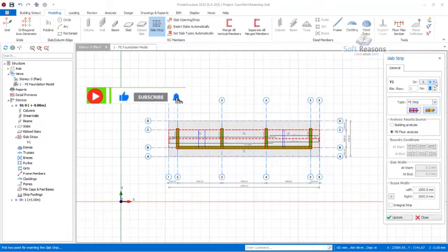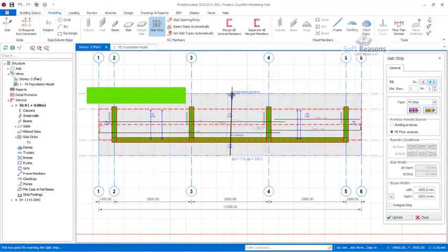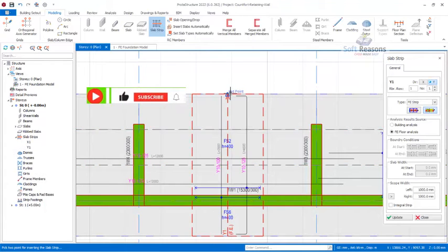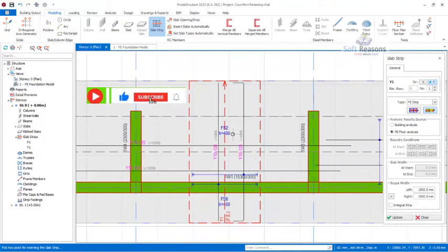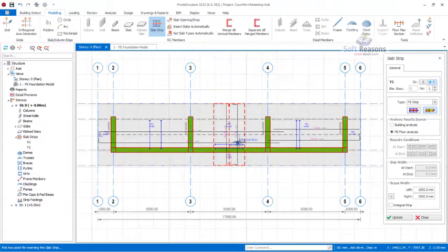Go to the Y directions, and then we also place this to generate the reinforcement. So we have also Y25 in direction 1 of the Y, and direction 2 is 100 spacing. You can see it right there. So we need to extend this. Pick this point and then pick that, click on update to have that extended all through the base